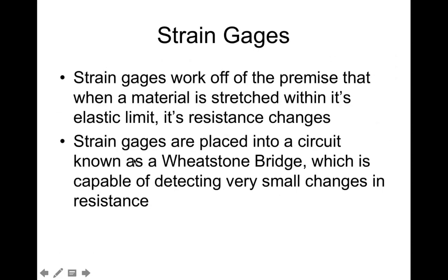And strain gauges are probably one of the most common ways of making very small measurements. One of the issues with biomedical instrumentation is that often the movement or the changes are small, so you're trying to make measurements on very small distances. If you're moving very small distances across a resistive element, then you're going to have very small changes in the resistance. What happens with a strain gauge is that as a material is stretched, as long as it's stretched within the elastic limit, the resistance of the material changes.